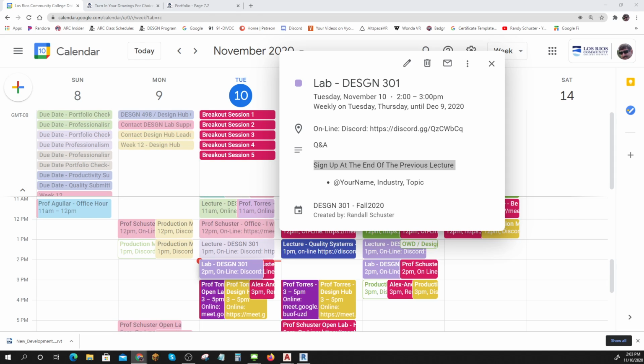Okay, so Nia, how do you use the press pull command on the Geneva gear and the angle on the tool brace? Okay, so that's pretty good. First of all, if the press pull command is not working for the Geneva gear, it means you don't have a nice clean drawing. There's little overlaps or little crisscrosses or something like that. So I'll give you an example of that.